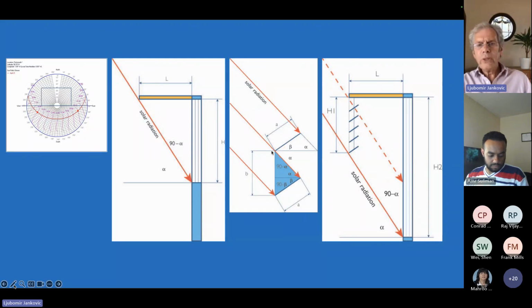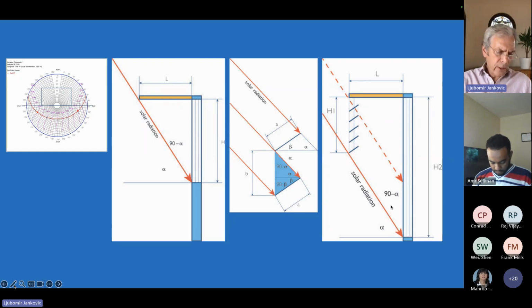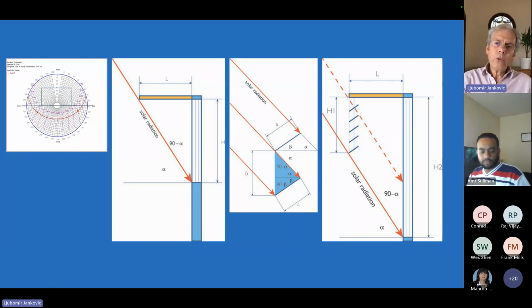And we can also design the louver blinds for that particular angle. But if we have tall glazing, then we can combine overhang and louver blinds to shade the entire height of the window. Otherwise, the overhang might need to be very, very long, which is not practical.